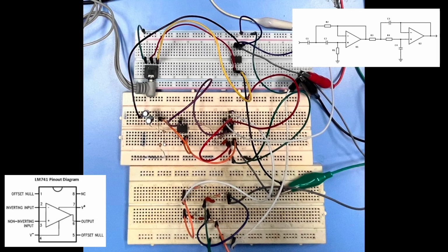And then if you can see here, the resistor connected to the ground is in the same row as capacitor 2 and the orange cable. And then in pin 7 here, the purple wire will connect to the low pass circuit. Pin 7 is voltage positive, and pin 4 is voltage negative. We also will connect to pin 4 at low pass filter.